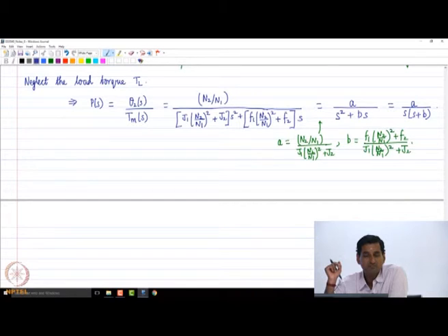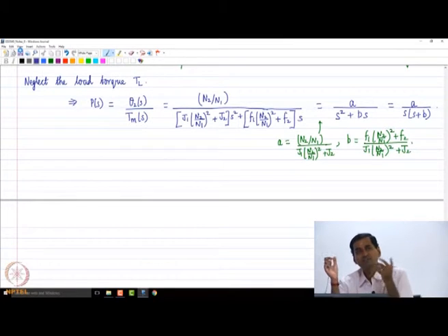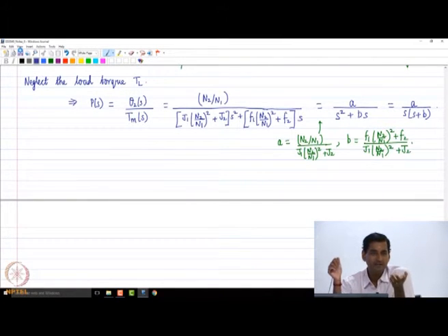So, is this plant going to be stable? No, right. Of course, it depends on how we look at it. As we discussed, some people call it critically or marginally stable, but we know that when we have a non-repeating pole at the origin, you give a step input, the output will become unbounded, right. So, you can immediately picturize it. Let us say you have a motor shaft and a gear transmission, you give a step voltage, you will see the output shaft will keep on rotating.